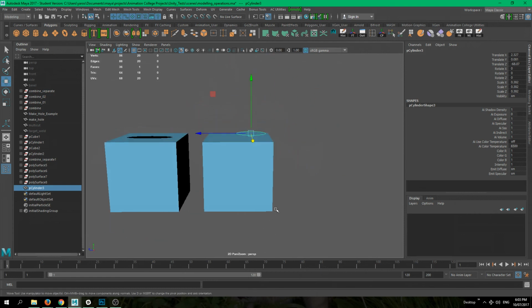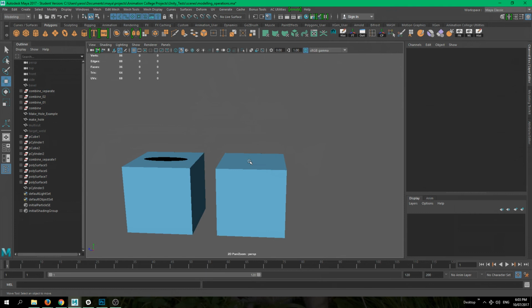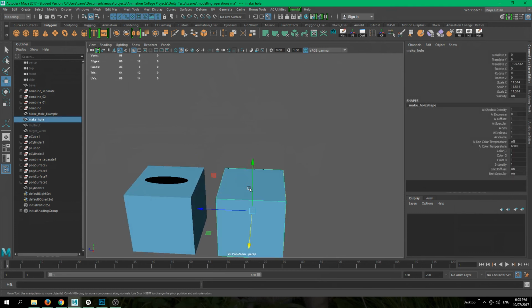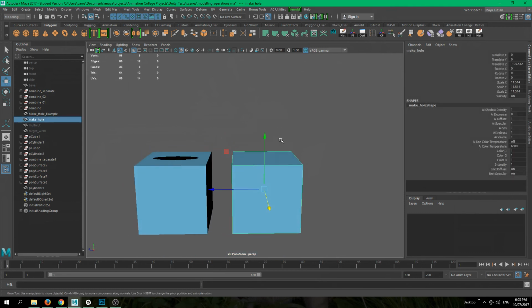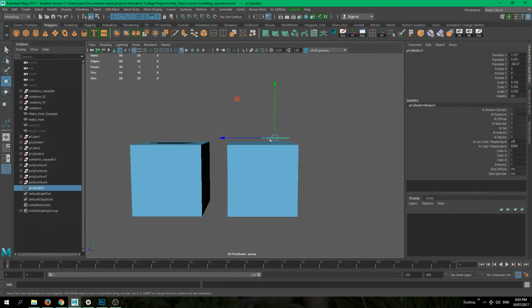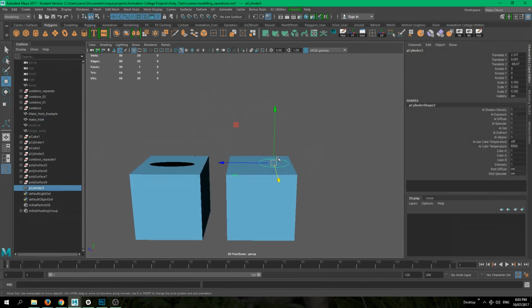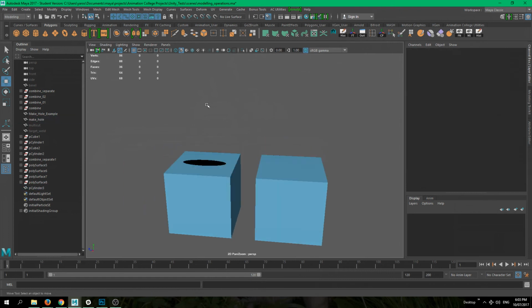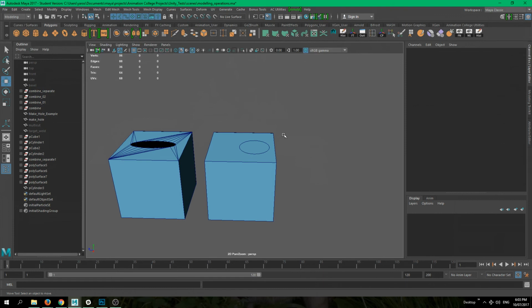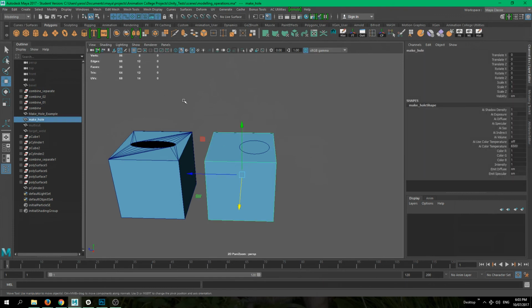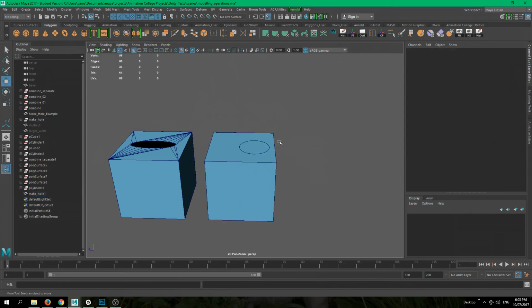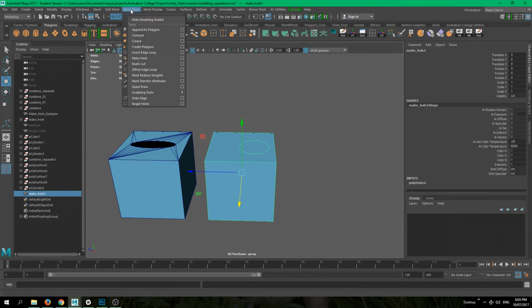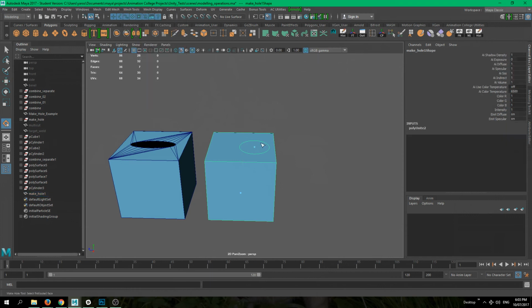And so one thing you will notice is that as soon as we use this command, what Maya will try and do, it will try and connect this polygonal face, and it will sort of make it go up, because this is not sitting directly on our cube, it is slightly above it. Now put our wireframe back on. So we'll have to combine those two elements together as well. Just mesh combine.